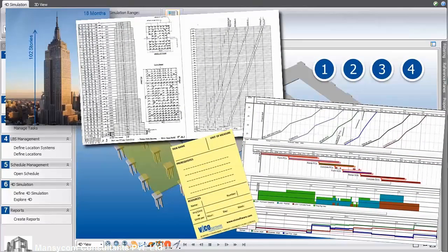It must be noticed that this is not a new method. It was in fact used on the Empire State Building with amazing results. It was a 102-story building in 18 months, and they used the location-based management principles to plan for continuous and aligned work with the emphasis on controlling the work. They used actual quantities per location to plan. They managed by production rather than just by the end date. And they were trying really to reduce the risk of that cascading delay that we'll see later.